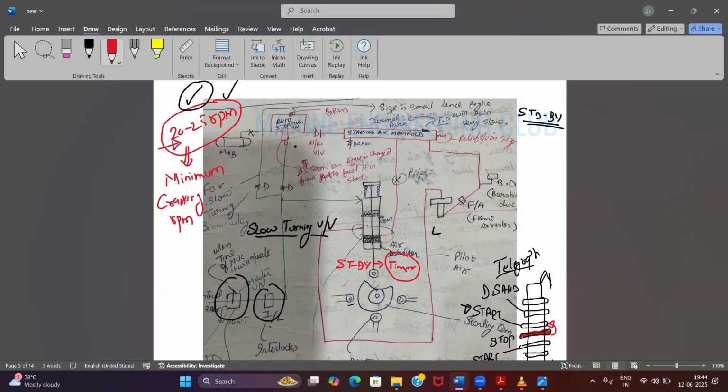For lubrication, you can just press the pre-lube button on your alpha lubricator. I have told you before, alpha lubricator session. You can press pre-lube. After starting the pre-lubrication, we start turning the engine.